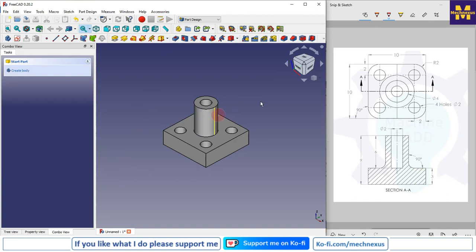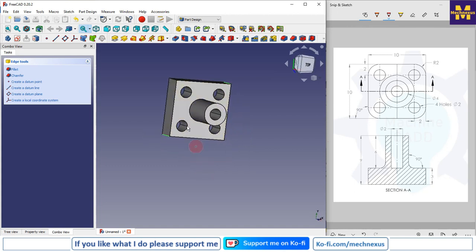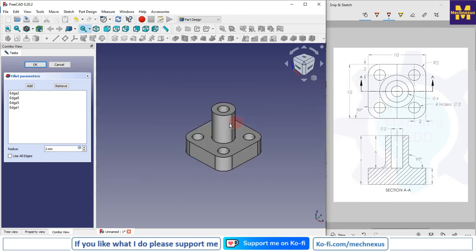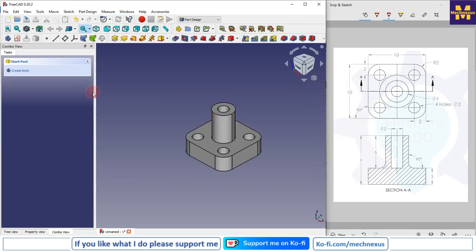Now the remaining thing is that we have to give R2 fillet at 4 corners. So I will select all these 4 edges, select the fillet, give 2 mm, switch to the isometric, and say OK.